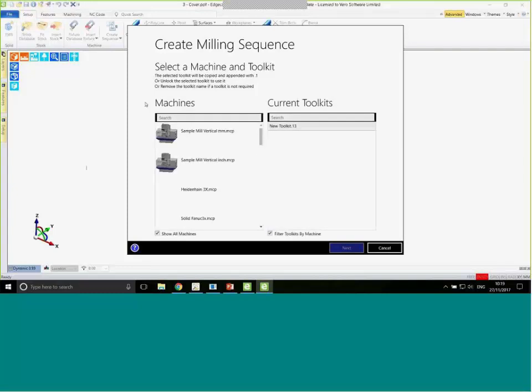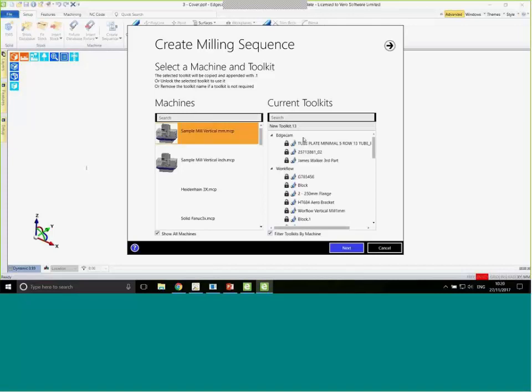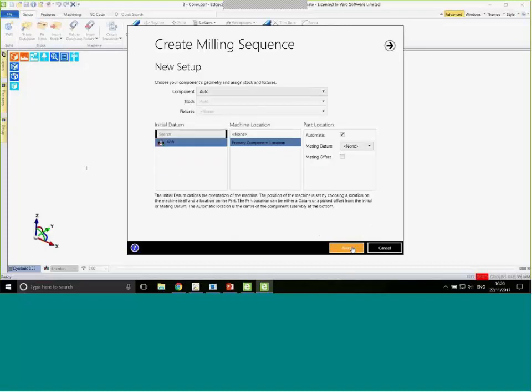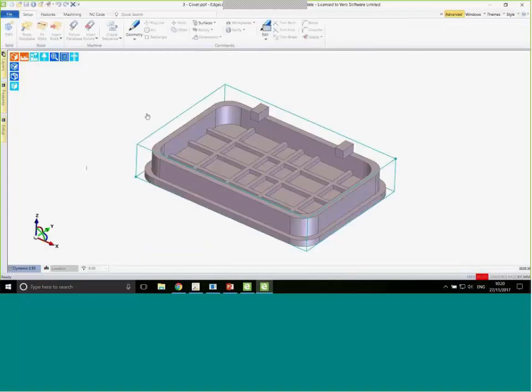These sort of people do tend to use a huge amount of datums, which are for clocking, datums which are to feed the component in. And here we see an example of it. It's just said, well, the only datum legally to be used here is the G55 datum. Over on this side here, it's using the location datum. So on a small part like this, maybe not very important, but on a huge tombstone, where you can have 30, 40, 50 different types of parts, it can become very, very cumbersome to wade through all these different datums. So now we have our datums clearly signified.